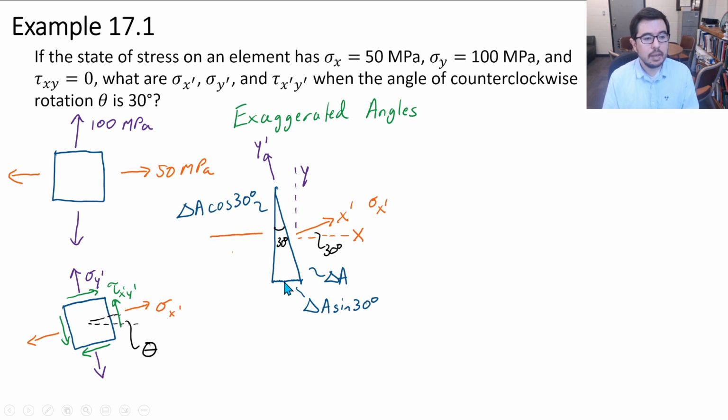And then when we start adding our other, or our original stresses, I guess I should say, we can also clearly mark the components. Okay, you see this now? This is now saying, look, I understand that sigma x is 50 megapascals, but like we said previously, this sigma x is not in the same direction as x prime, and is not in the same direction as, say, our tau x prime y prime.